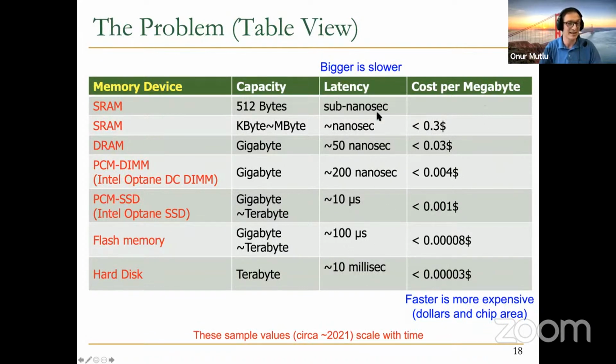But latency is a very different beast. It's much harder to improve because you're dominated by the interconnect. And for interconnects, essentially the length of the interconnect and the speed of the interconnect do not really scale well with Moore's law or packing more bits in a millimeter square. You need some other technology to scale the latency. That's why the latencies are not scaling.